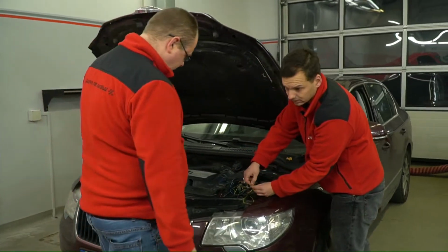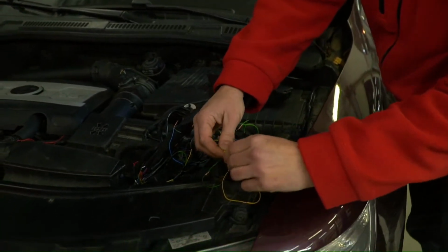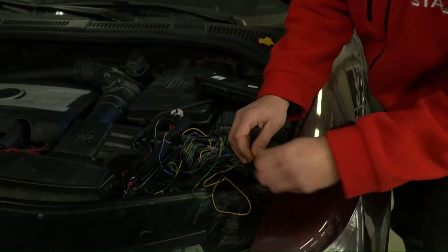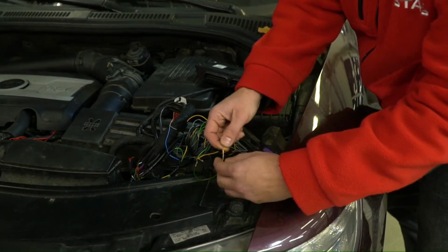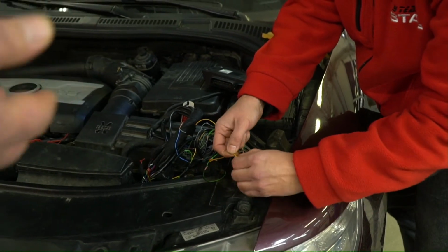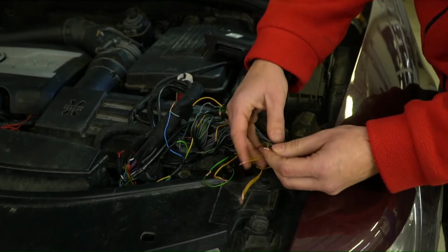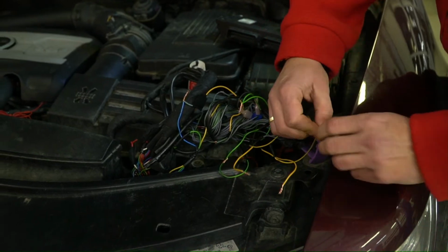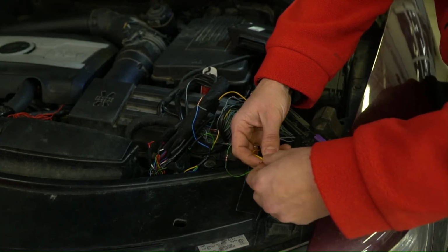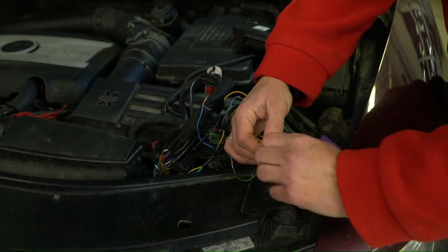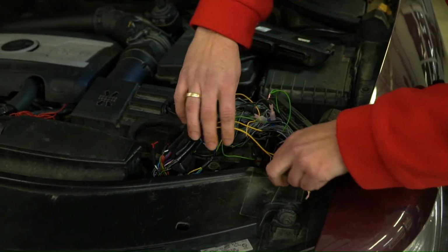Yeah, let's go. And we actually swap the signals. Just to show you what is going to happen when you connect the colored wire the wrong way. Right now, the wire reading the signal from the petrol ECU is connected directly to the injector, and the wire emulating the signal for the petrol ECU is connected to the ECU, and in that case, the petrol will flow as on the petrol without the gas system.